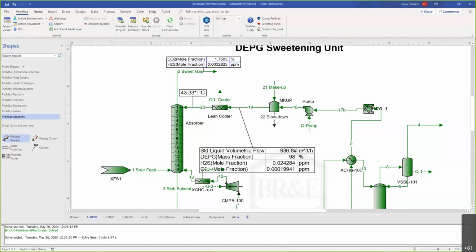So Hussein has asked, is MDEA more selective towards CO2 or H2S? So MDEA, methyl diethanolamine, it's selective towards H2S. So we say that it slips CO2. And again, that's the reason that we have activated MDEA, because in cases where we don't want to slip CO2, where we want to capture all of the CO2, we need to add an additive like piperazine to capture the rest of that CO2. So yeah, when we talk about MDEA being selective, it's selective towards H2S, it slips CO2.